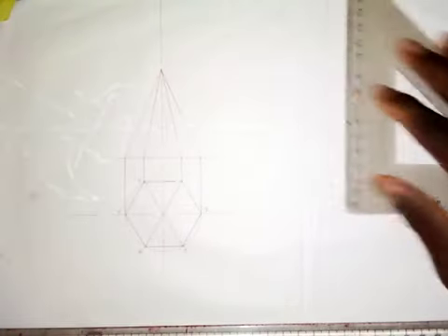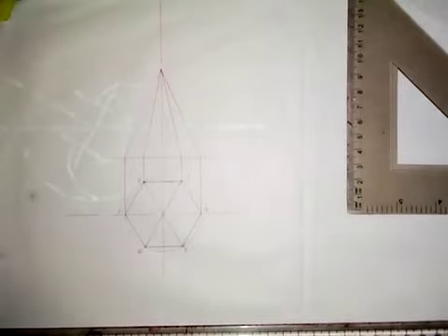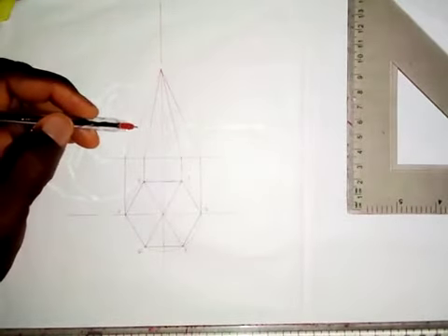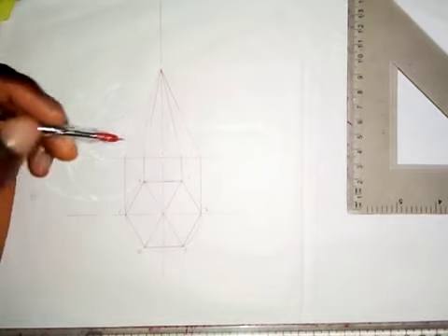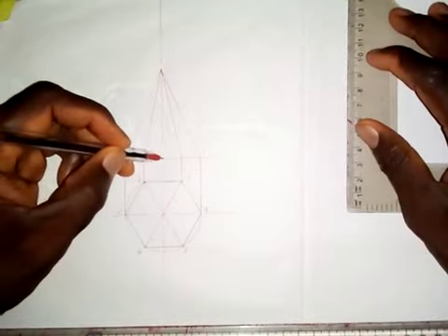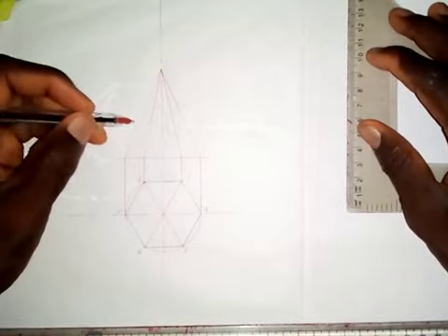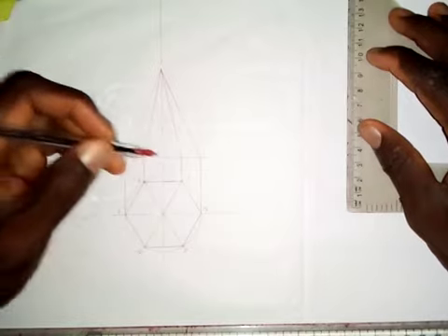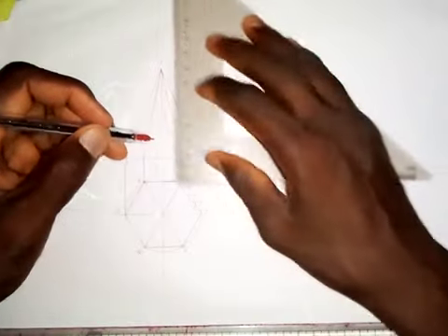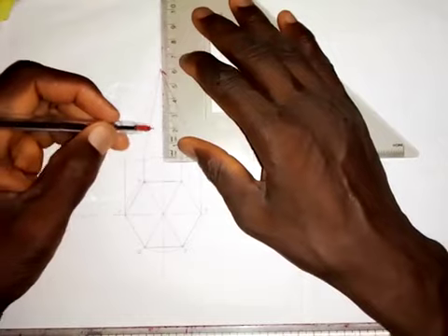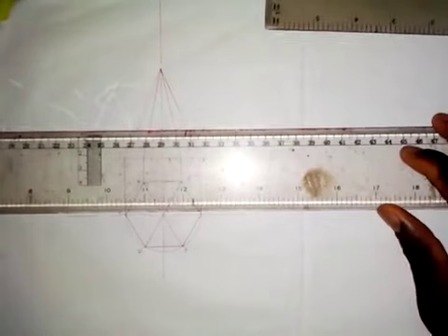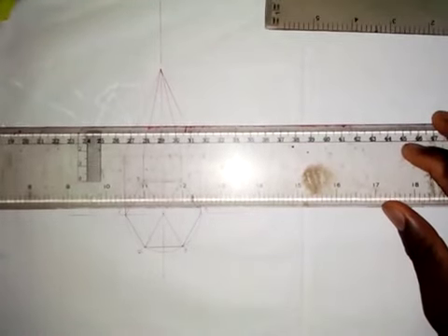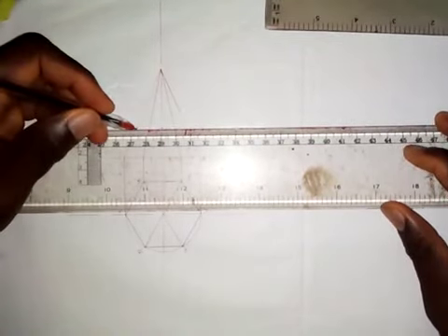Okay, so now, as we have in the question, the point at which the cutting plane touches this side is 10 millimeters. So if you multiply by 2, that is 20. So that 20 millimeters, we are taking it on the vertical center line. You can't take it on this side, it will not be accurate. So you take it on the vertical center line. So I will take a measurement of 20 millimeters here. This is 20. Then I will locate it. I'll just trace it to this slant side on the elevation. So this point, this is the point.